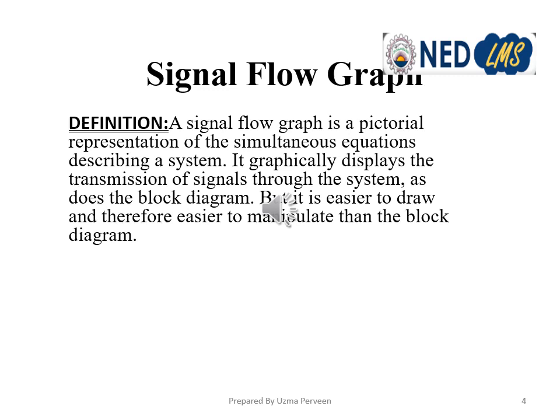This method was developed by Mason to determine the relationship between system variables based on the line segments. The advantage of this is the availability of a straightforward method for a complicated system to find the transfer function, and another advantage is the availability of the signal flow graph gain formula, which provides the relationship between the system variables without any complicated reduction procedure or manipulation of the flow graph.